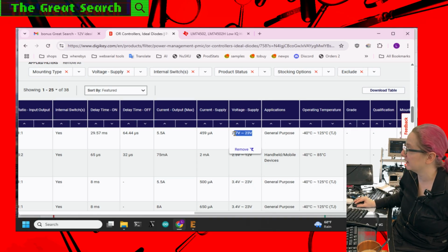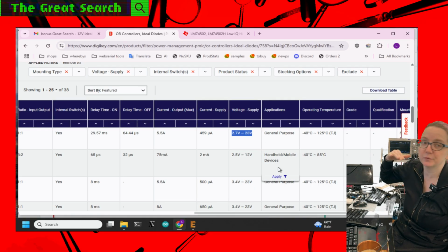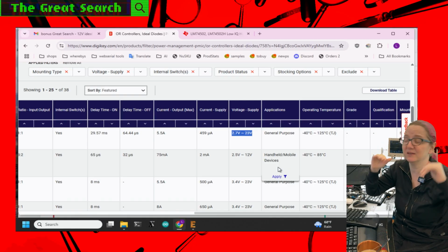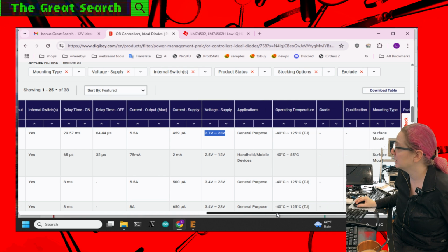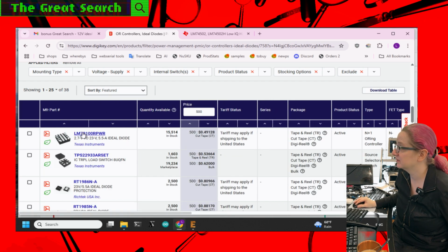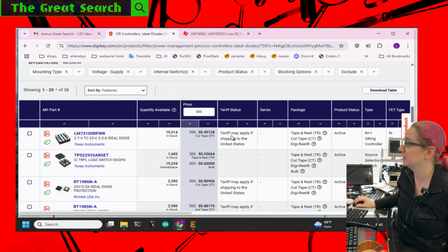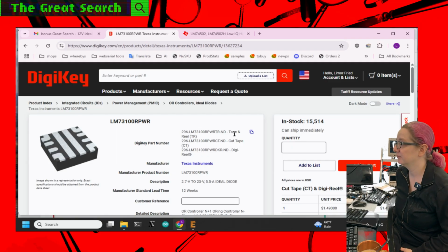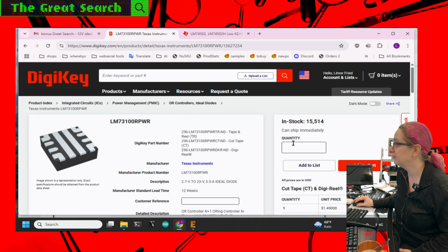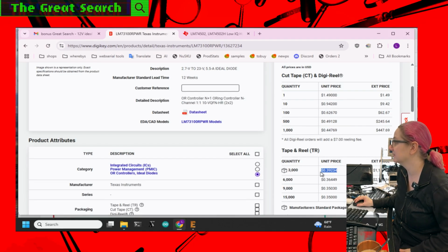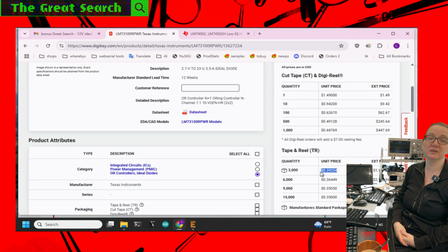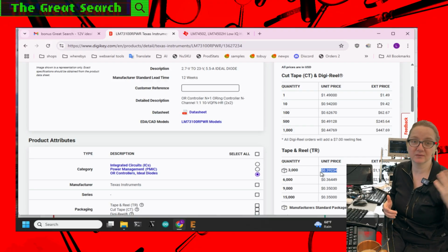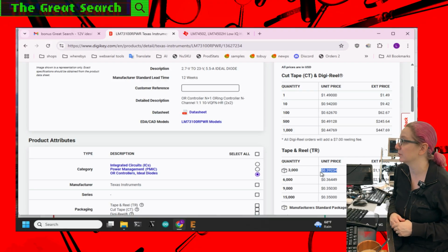And so if I wanted to use it with higher voltages, because sometimes solar panels go a little high, like a 12-volt panel will actually float at like 15 to 16 volts. So I actually kind of think I'm going to go with this one. It's kind of got a weird, funky package here. But 5 amp, which is great, up to 23 volts also, looking good. It's a funky package with lots in stock. And the price is, like I said, on par when you get into the real quantity with a Schottky diode. It's twice the price, but you get so much better performance that I think it's definitely worth the upgrade.